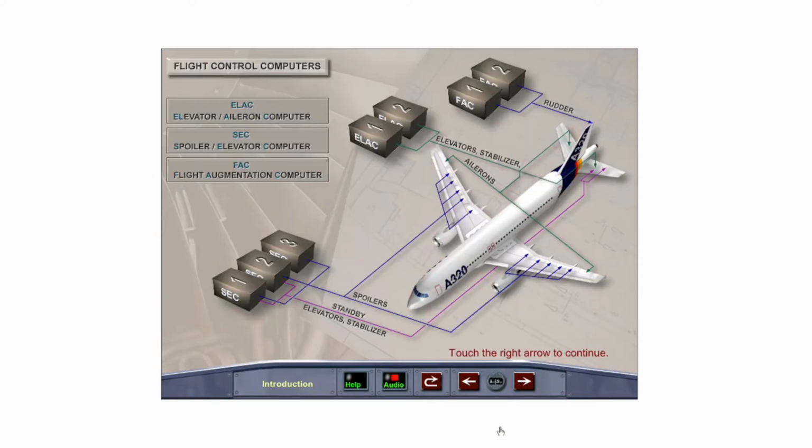Flight control is achieved by 3 types of computers arranged to provide redundancy and failure protection. Different manufacturers, different hardware, and different software have been used to eliminate the potential for common errors. Electrical power sources are also from different electrical buses.